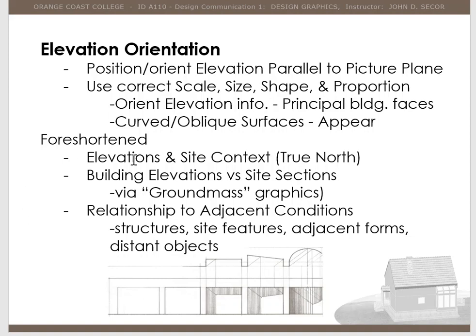Now, often we might foreshorten some walls and so forth, and we want to do that to give it some depth. But we often will put a very heavy line at the bottom. This creates a ground mask, letting you know that this is mounted on the ground. So a heavy line at the very bottom is extremely important when doing exterior elevations. It gives us the indication that this is the ground or earth. So it's a very heavy line. We also make sure the outside structure has a nice heavy line to indicate it is structural.